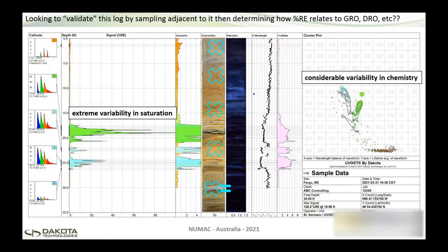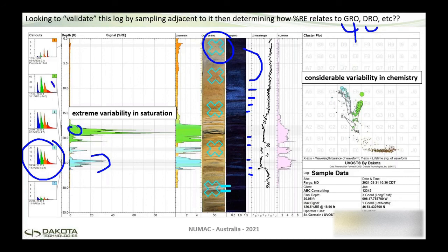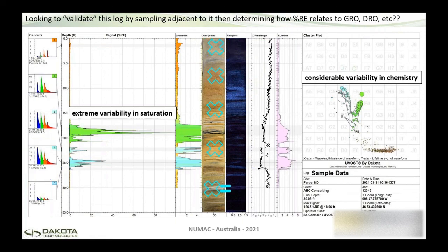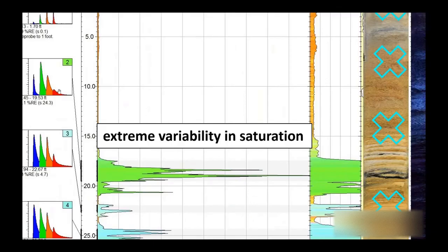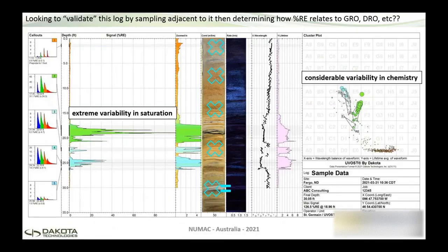because what was really happening is there are layers of fluorescence, because there are layers of NAPL-affected strata. And where you take your sample is going to have a tremendous impact, orders of magnitude changes in concentration of GRO, DRO, right, depending on where you took your sample. This, for instance, is intact gasoline, way higher in GRO. This is fairly weathered, or it's maybe even got some incorporation of diesel. You see that short, long, long, long? Might even have some diesel in there. We don't know because we never sampled and did the analytical chemistry.